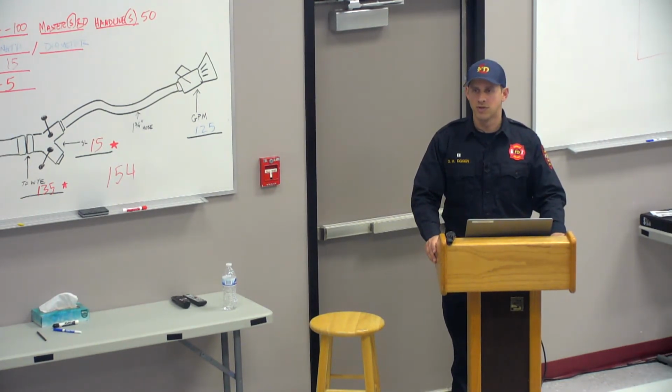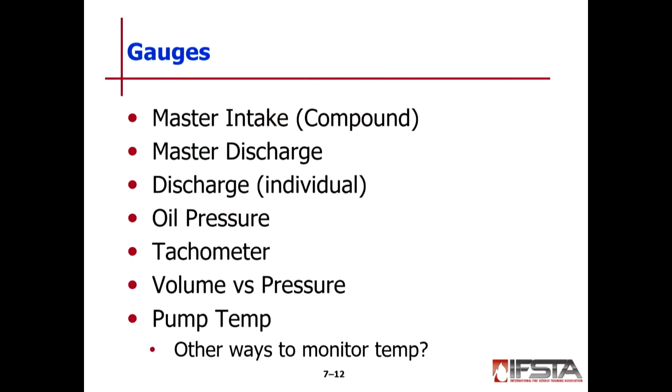So we can open up doors and get airflow moving through the apparatus. We can recirculate water. Does anybody know what that actually is? Like how you recirculate water, what you're using? Tank fill and tank pump. Yep. There you go, tank fill, tank pump, or put a booster line in it, but you gotta have that tank fill open. You start dropping water out of your overflow, right?